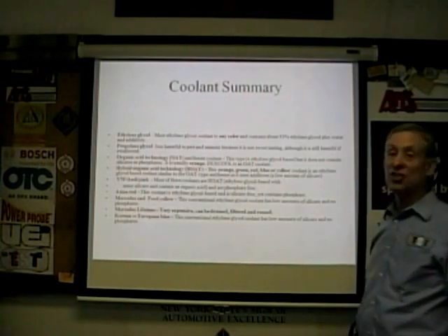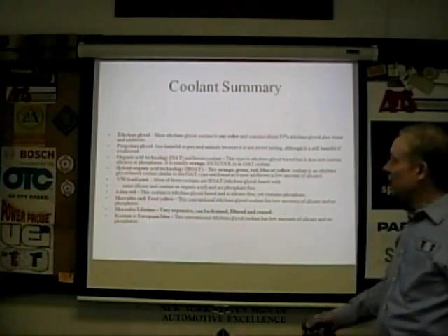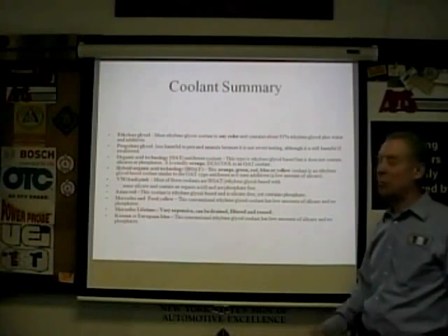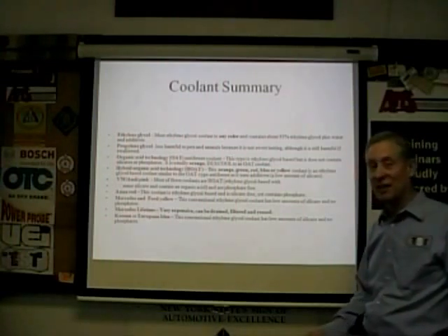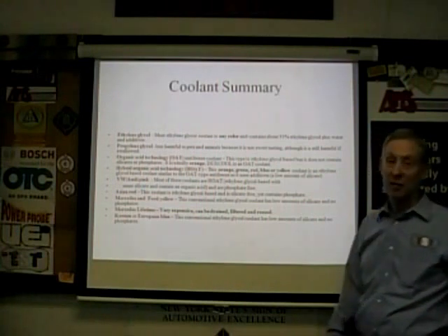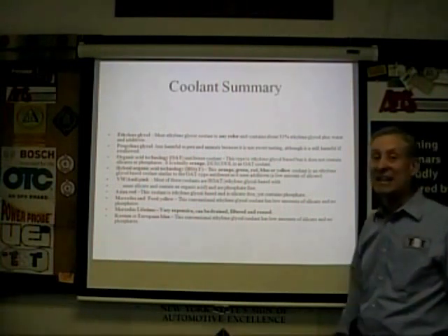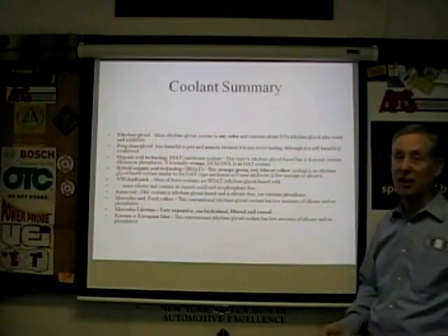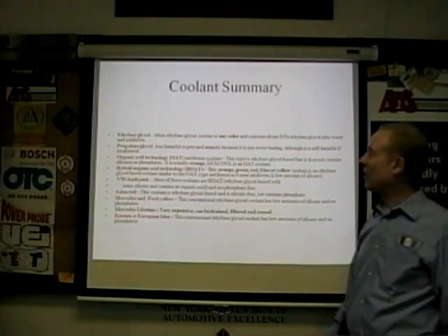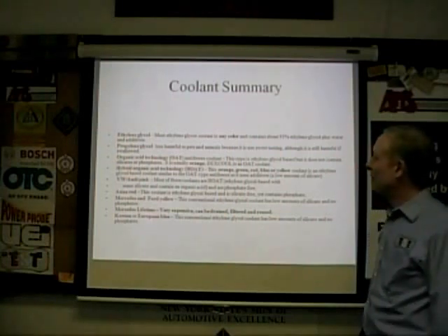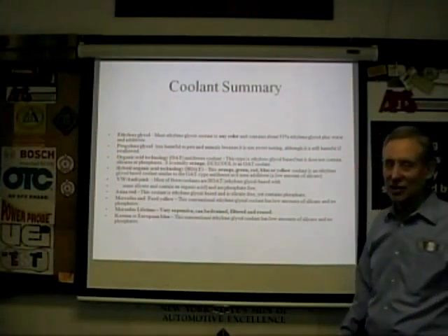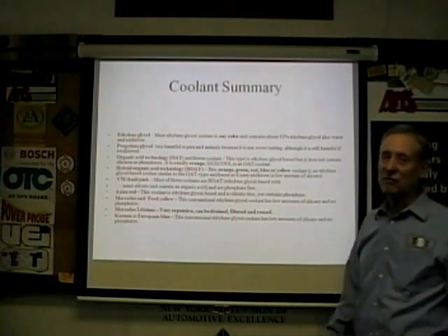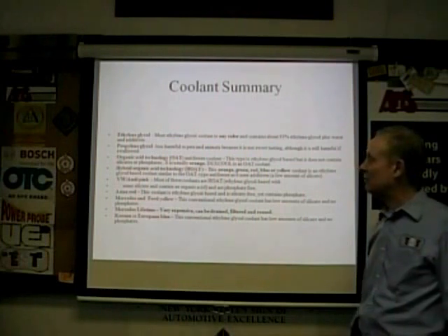All right, here's a summary. Ethylene glycol, that's really what's out in all the OEM fills. Propylene glycol can be sold to you by some salesman, and it's really not recommended. I don't recommend it at all. It can't handle the heat, for starters. Less harmful to pets. They tell you it's not toxic at all. Give me a break. It's a chemical. It is harmful. OAT was the old technology, the green stuff, Prestone from the 70s, whatever. Hybrid is kind of the new dominant technology.